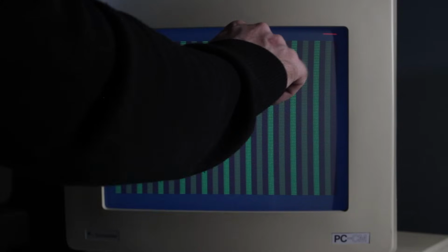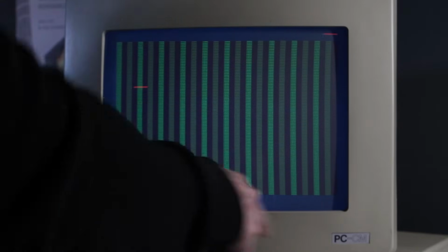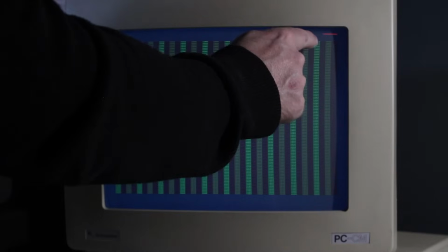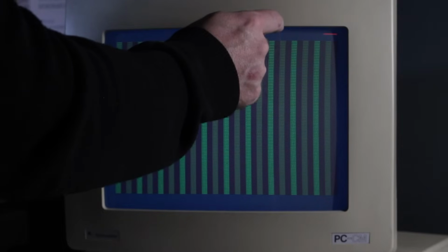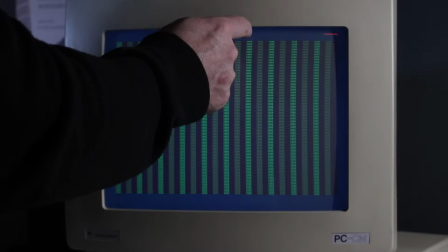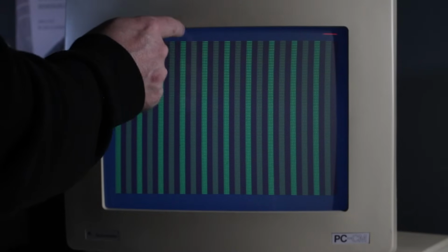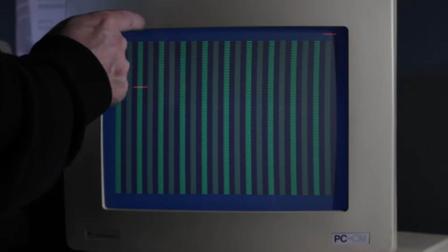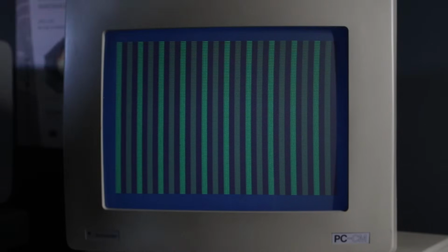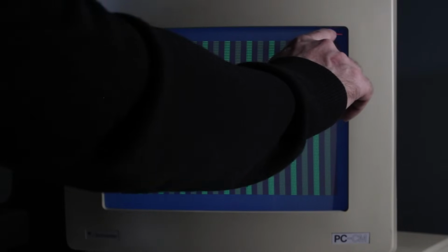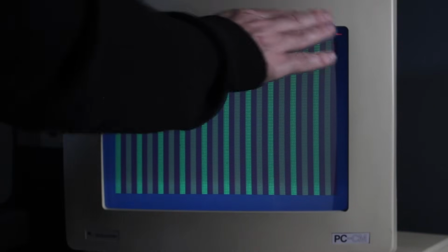But then I start the interrupts running, and I make them 1 character short per frame. So it'll always end up doing the interrupt 1 character earlier every frame. And every frame I poll the status bit in exactly the same point in the loop, and eventually it will hit the start of the frame. It takes quite a while. You can see it's like 1 or 2 seconds to do that. And eventually it'll say, now we're at the start of the frame, and that's how I measure it.